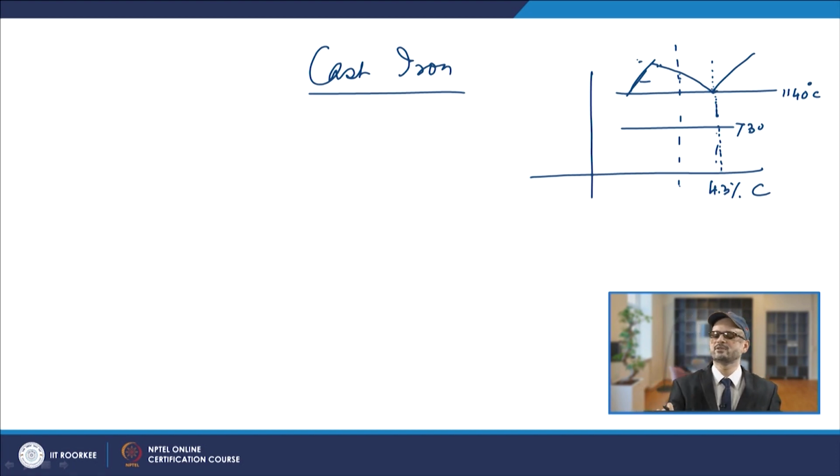So, you will have austenite plus ledeburite. If you go to the hypereutectic side, you will have cementite, or in fact, when we talk about cast iron, because of slow cooling or the presence of certain alloying elements, you get graphite. So, you will have graphite flakes coming up, and then the ledeburite composition.